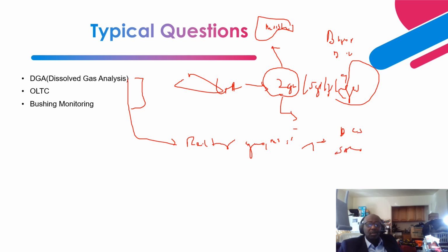and this is sent to your DCS, your SCADA system, through an RTU. Sometimes some of these DGA devices can drift. There's something they call drifting, which can provide a false indication of gassing. So anytime you receive an alarm from your SCADA system, your DCS system, or your local HMI system, what you want to do is collect another oil sample and send it to an independent lab for validation, to make sure that it is a true gassing situation that you are receiving.